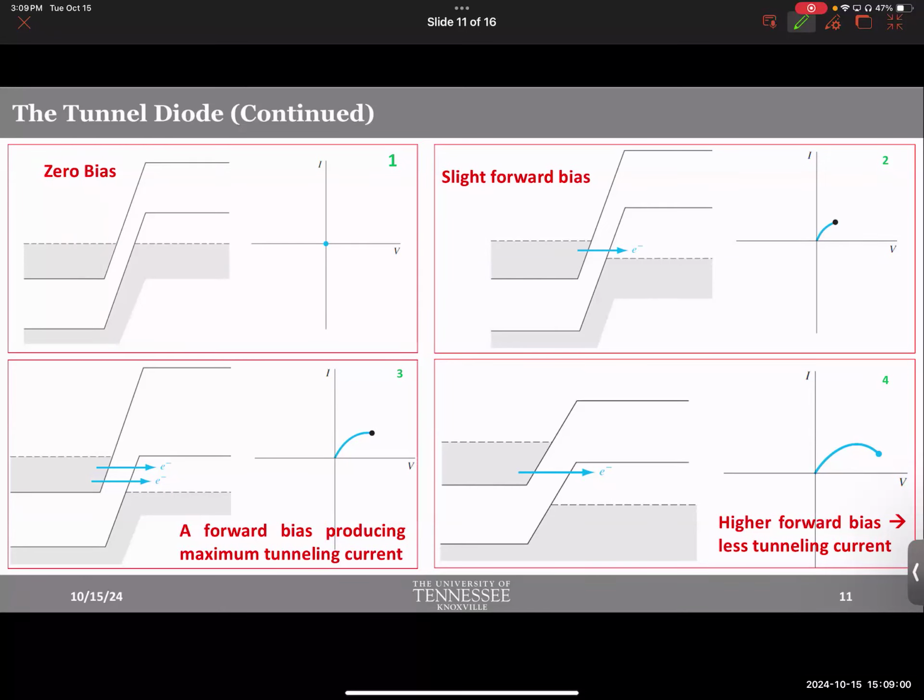So please pay attention. This was our Fermi level here. As we apply a negative bias, this Fermi level should go up with respect to the other Fermi level. Now, as the Fermi level goes up, notice, why have I made it gray? Because I want to indicate that there is a lot of electrons available. So this is your conduction band, by the way. This is the Fermi level. Electrons should be available up to the Fermi level and above the conduction band. So these electrons are ready to conduct because they are already above the conduction band. Am I making sense?